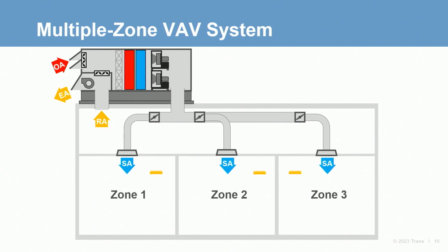At the same time, air naturally moves from areas of higher pressure to areas of lower pressure. In this diagram, the air handler has a relief fan exhausting air out. There are other methods to relieve air from the building that we'll discuss later. Some zones may have separate exhaust systems to remove stale air. Common examples include bathrooms, locker and shower rooms, kitchens, salons, and art classrooms.